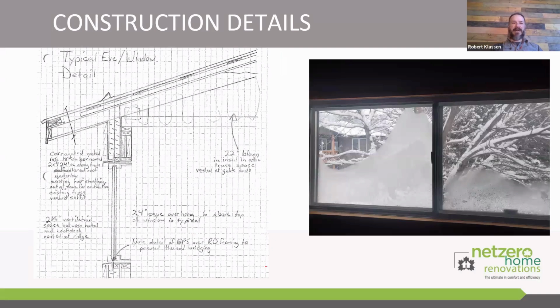There's a quick construction detail just showing we did something a bit unconventional. We used a flanged window. As Chelsah mentioned, we used the Gentek JWC 8500 window, and it was a flanged window, which I went with for ease of installation, because most people in the construction industry are very familiar with installing flanged windows and seemingly less familiar with installing a boxed window, which tends to be more common in a really high-end window.